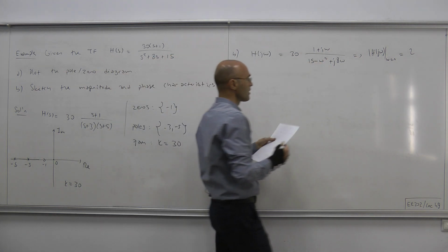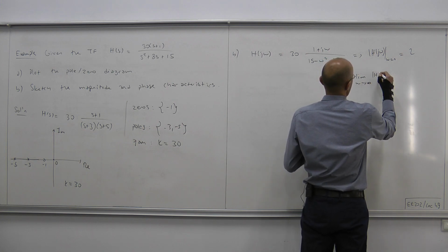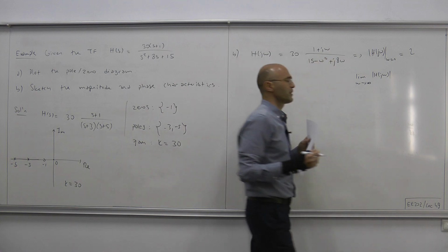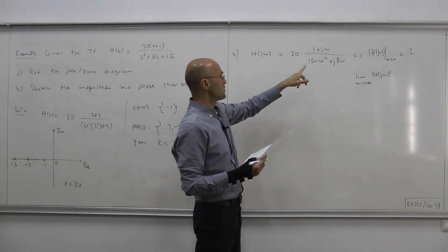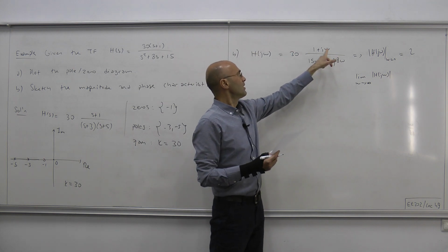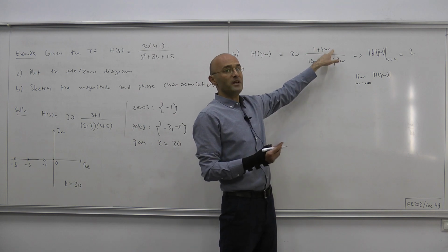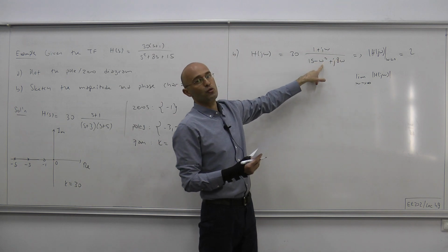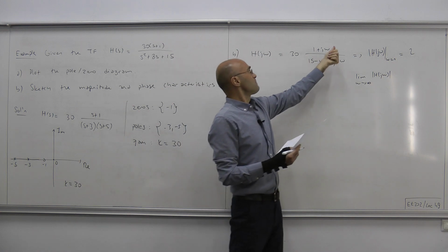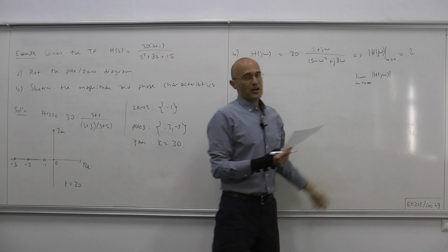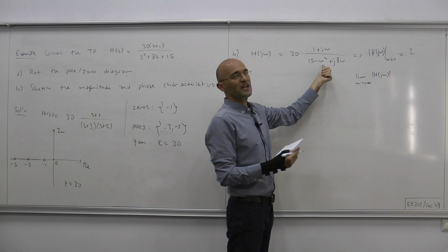And what happens as the frequency becomes larger and larger, so what happens as omega goes to infinity? Now, as omega goes to infinity, j omega dominates the numerator and minus omega squared dominates the denominator. Therefore, as for the gain, this fraction converges to omega over omega squared.